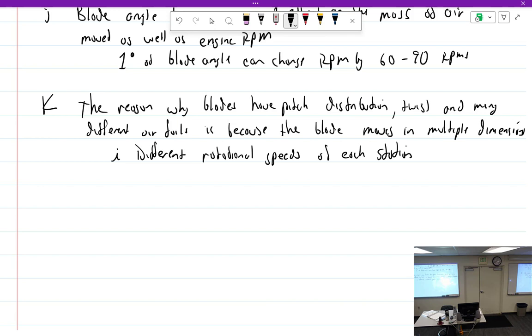I often talk about propellers as a plane of rotation. And I think about it as a solid disc almost, the propeller disc. So you can think about it the same way. But if we do it like this, just watch right here in the hub how slow that goes around. You can see every single rivet, right? Now try and do it up here. It's moving a lot faster. Miles per hour wise, this is really going fast out here. It's got a longer distance to travel to get back to the original too. And the further out I get, the faster it's going to go. So out here, it's turning a lot faster. In here, it's turning a lot slower.